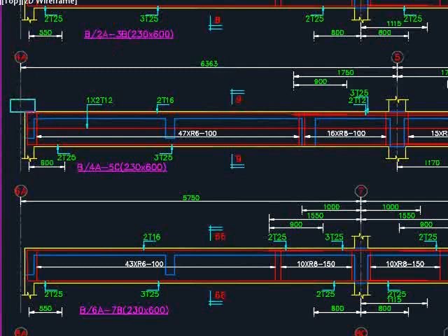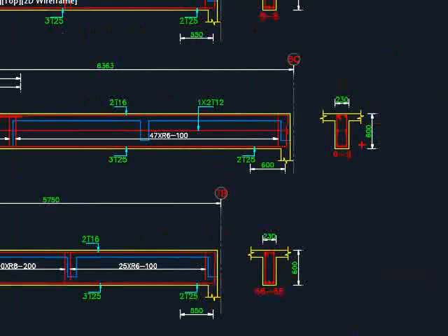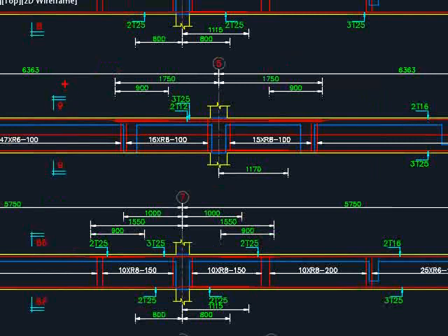It would be good if you indicate the distance clearly so that the contractor has some idea without requiring to refer to the structural key plan. There will be cut sections, which based on the section 99, should look something like this. Theoretically, you should have every single stretch of the members to have cut sections, but this is going to make the drawing rather messy.